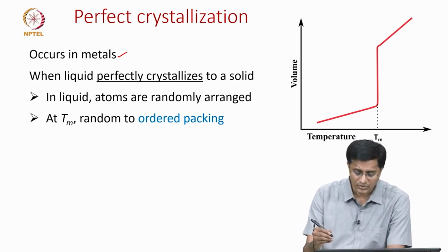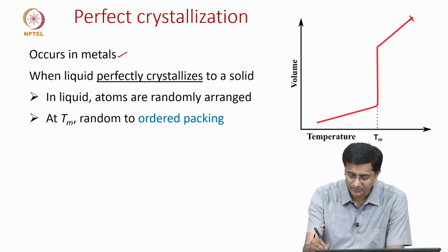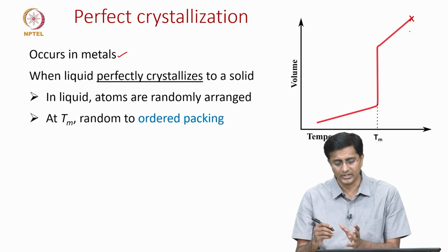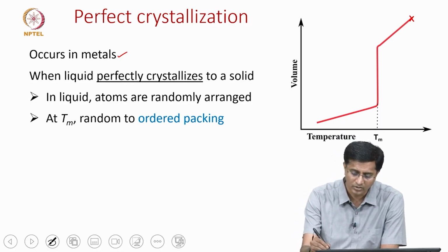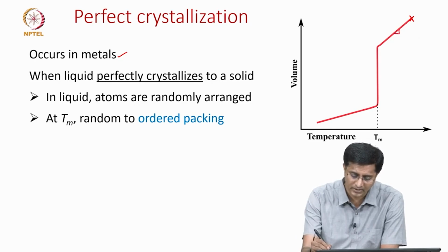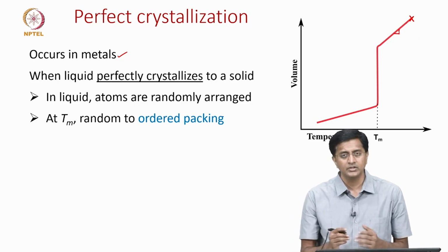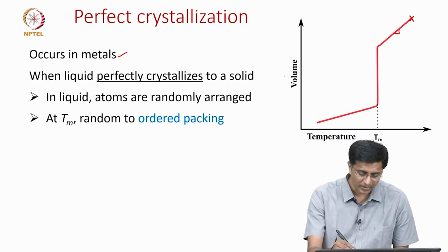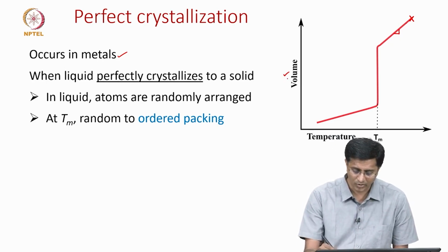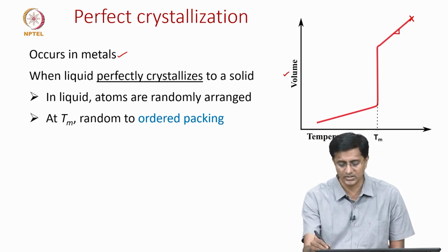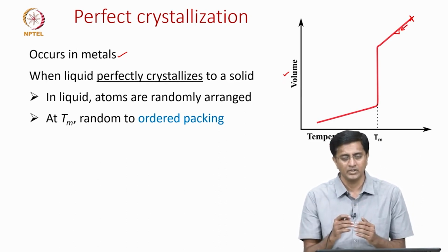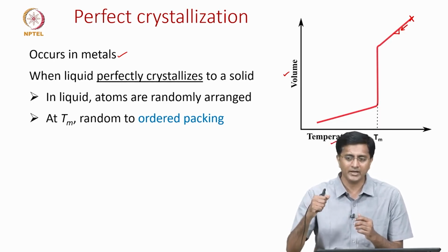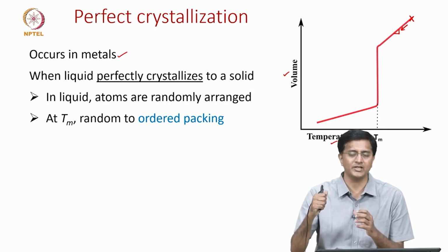So, we are starting at this point where the temperatures are high and then we are cooling down. Initially, when we cool, you see a linear slope downwards. Why does this happen? On the y axis is the volume and on the x axis is the temperature, which means as we are cooling, the volume is decreasing. Why does this volume decrease? The answer can be explained by looking at what happens to the polymer chains at high temperature.